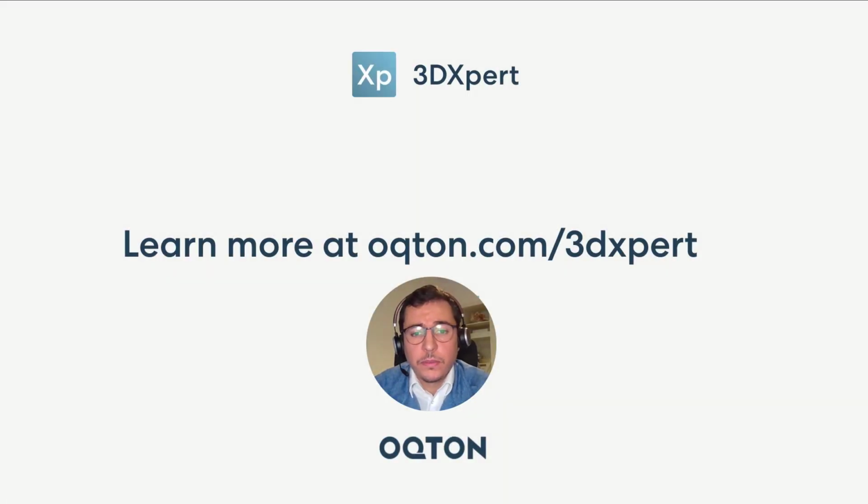And that's already it. The super easy workflow in 3DXpert in combination with EOS Sprint, where you can just continue working with your solid file, do all the work in 3DXpert, have still material parameters management and slicing done by EOS Sprint, but you still just click on slicing in 3DXpert and export the OpenJZ file and put it on your machine. We also have a workflow where 3DXpert uses the EOS Sprint SDK to directly communicate to the machine and sends the task file immediately to the machine.